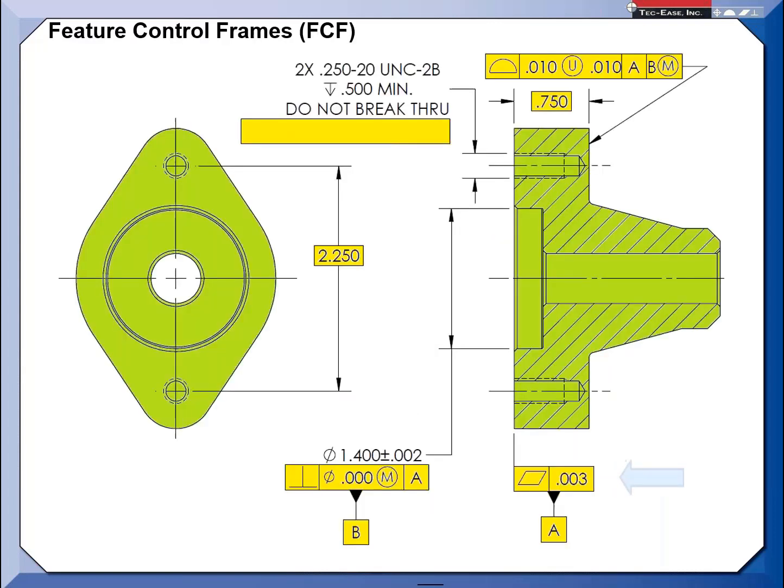Same thing over here. We've got the same flatness control, same issues, same problems. So what winds up happening is, if this is a hogged out machined part, depending on how this flange acts, yeah, you can get some distortion in there. The tolerance zone is 2 parallel planes. What happens if this one comes in this way? Well, that may not be good, right?